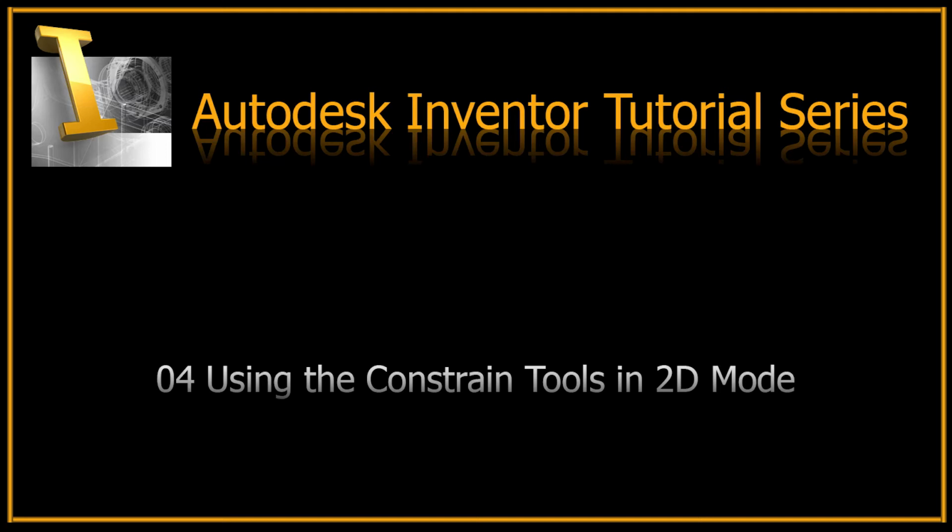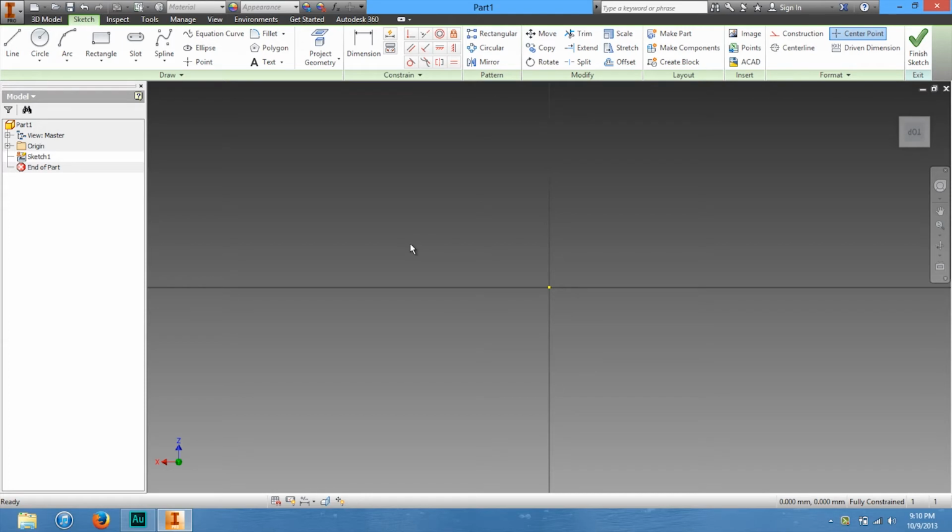In this tutorial, we'll go over the constraint tools in 2D mode. So if I wanted to make a line a certain length, I'd use the general dimension tool in this box of constraint tools over here. With newer versions of Autodesk Inventor, you can just type in the dimension right when you're making the line. So if I want a 16mm line, just type in 16 and press enter, and now that line is 16mm, and I can continue on.